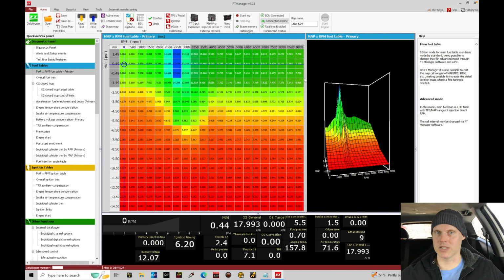And if you don't have a chassis dyno, that's where you're at. You're only going to take a look at the log data. To evaluate what the engine's doing and how it's responding, you'll have to watch what your fueling is doing. If we're seeing positive gains, the O2 correction is going to add a lot more fuel. And if we're losing power as we're adjusting the variable cam timing, we'll find it's going to take away fuel. We can get a feel for what's going on with the engine pretty quickly as long as we're paying attention to the details I outlined in the training module.